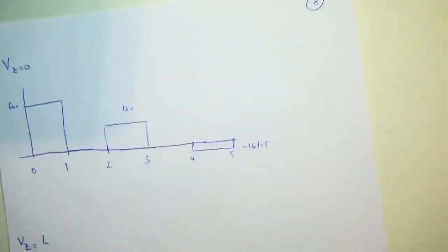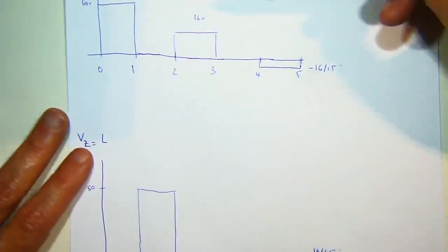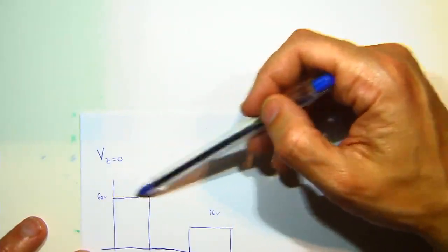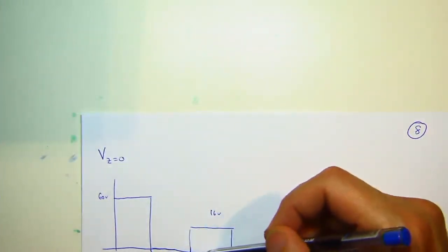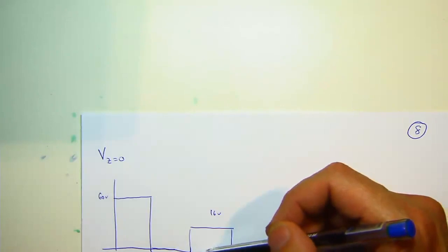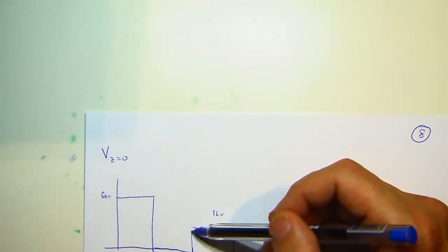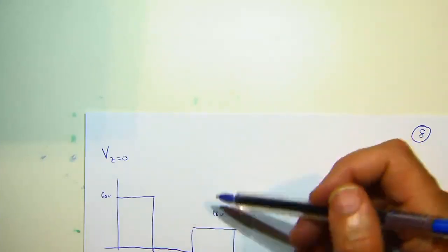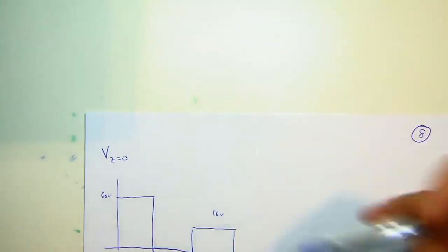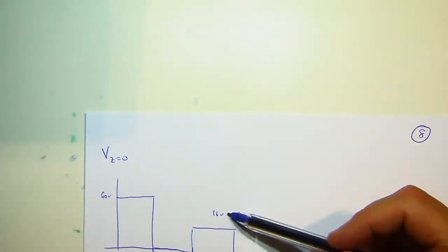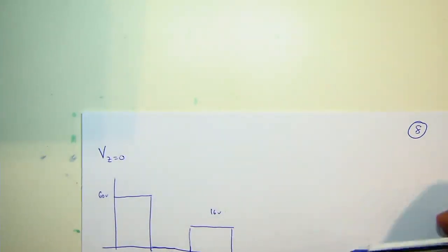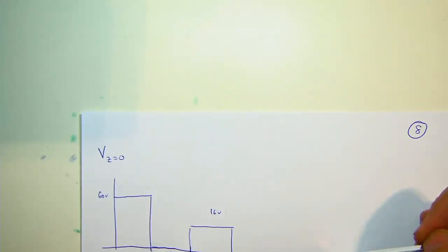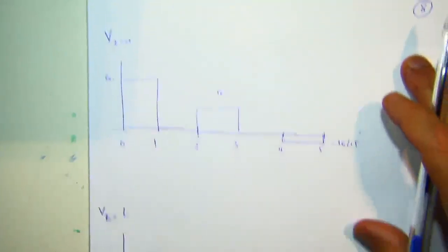If you go through the analysis, what you're able to convince yourselves of is that at the source, initially for 1 microsecond you've got 60 volts. There's nothing after that for the next 1 microsecond. You now get the reflected signal coming back at you, but you also need to meet the boundary conditions. So instead of 20 volts, you get a 4 volt reflected wave, so the voltage at the source is minus 16 volts, and that situation continues. For the 4th to 5th microseconds, you get a voltage of minus 16 on 15.